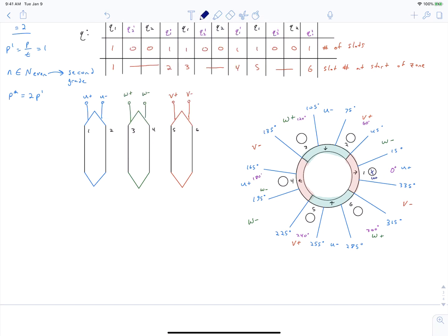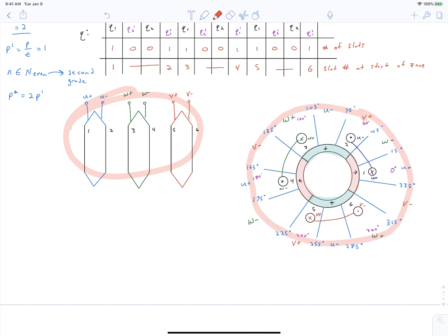And so what we've done is just working off of our winding schematic here and adding those labels as we go around to the slots is the following. And we've again ended up with a concentrated winding, but the winding coil side placement does not match what we would normally expect based on our zone diagram when we have evenly distributed zones.